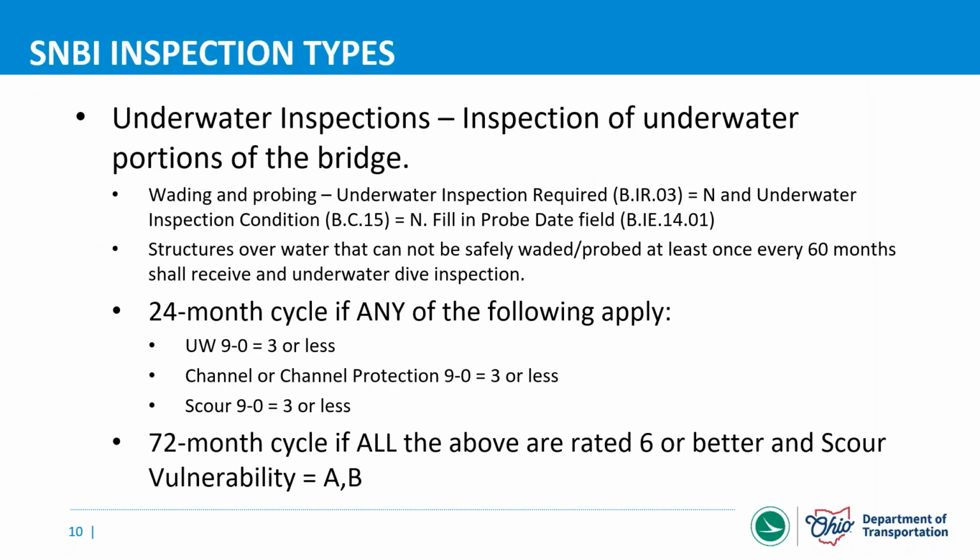And then also the underwater inspection condition, BC15, the 930 for specifically the underwater components, is also N unless you have BIR03 equal to yes. So unless, again, you have an underwater dive inspected bridge, you will have N for BIR03, underwater inspection required, and BC15, underwater inspection condition. Now, if you are doing that, we do expect you to fill out the probe date field, right?